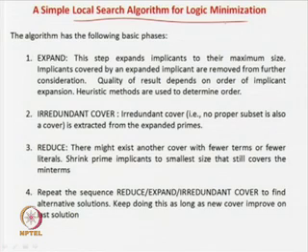So this heuristic for logic minimization, Espresso, has its own way of searching the neighbor space. That we are going to see, but again emphasizing, we are not starting with any kind of prime implicants. It has very basic 4 steps. First step is expand. This step expands the implicants to their maximal size. Implicants covered by the expanded implicants are removed from consideration. I will tell you what it means.